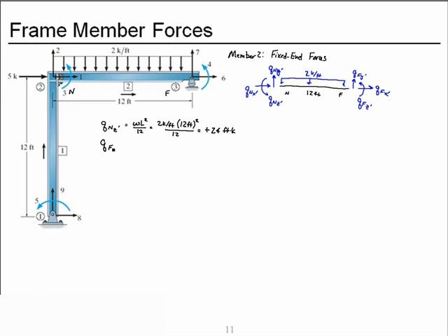Q at the far end, and these are all with the subscript not, because they are fixed end forces. And so getting back to our calculation, for the far end, fixed end force will be minus omega L squared over 12, so it's a minus 24 foot kips. And we're going to need to convert these to the same units that our stiffness coefficients use, which are inches and kips. So if I take this quantity and multiply it by 12 inches per foot, I'll get a positive 288 inch kips. And here we'll get a negative 288 inch kips.